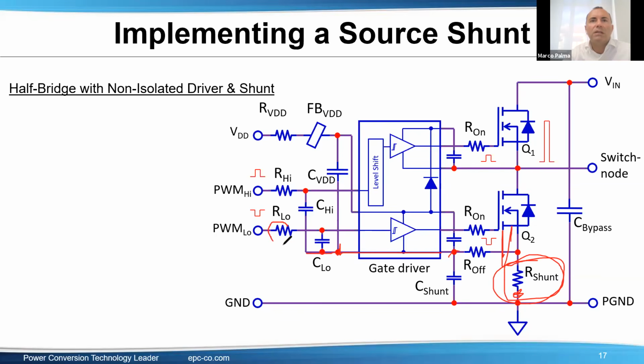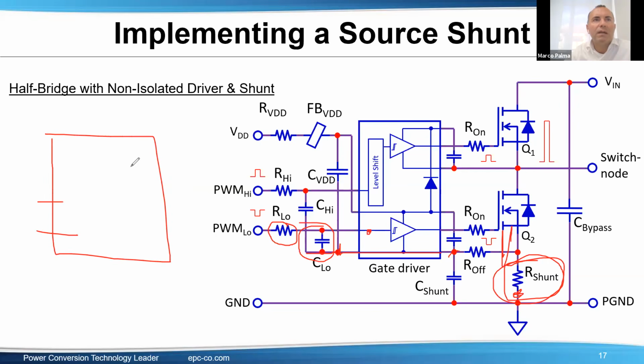And then what we suggest is having an RC like this, so that you make sure that these thresholds are not causing unwanted turn on or turn off. It's not really easy. If you have a severe problem, the best thing is to have the low side with the commands, and then your high side with a level shifter, and then you need to have also a level translator here, so that the low side ground is really decoupled from the signal ground.